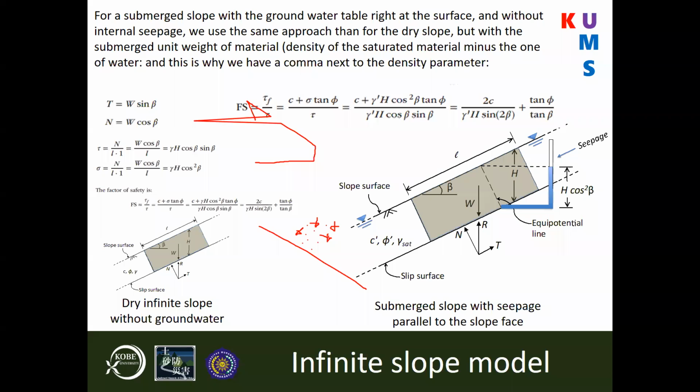So you have water in the middle. That water is not going to resist the downward movement when you press normally. So when you have normal stress acting on a mass of sediment, the sediment themselves will resist that movement before sliding. The water does not.